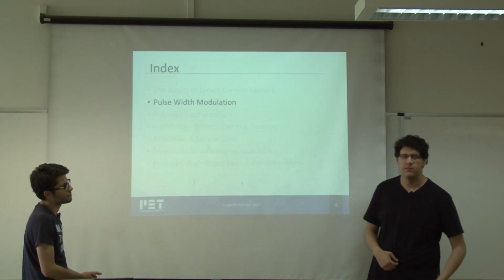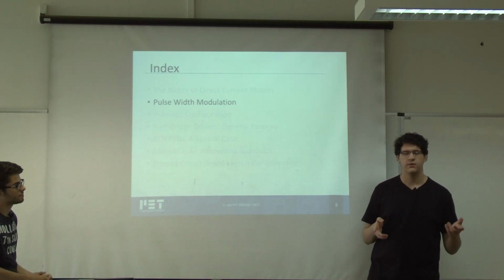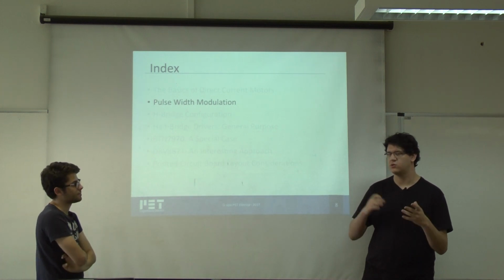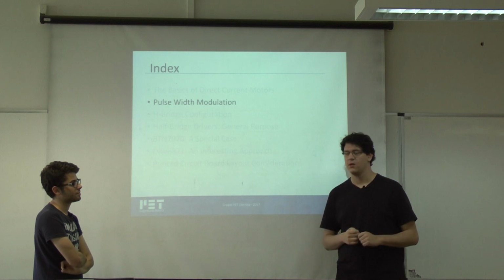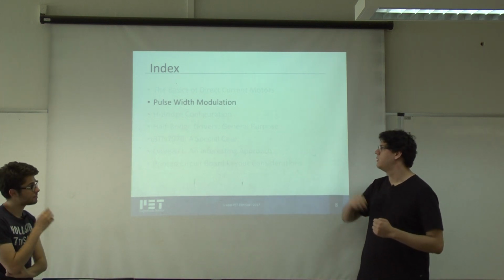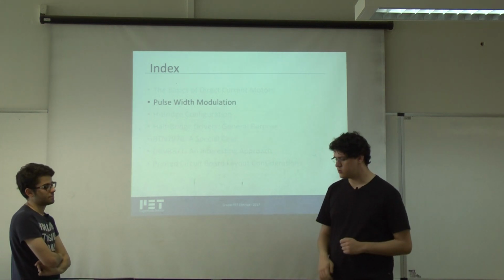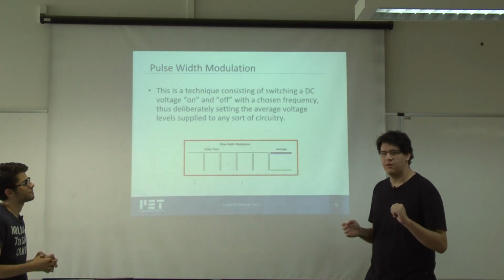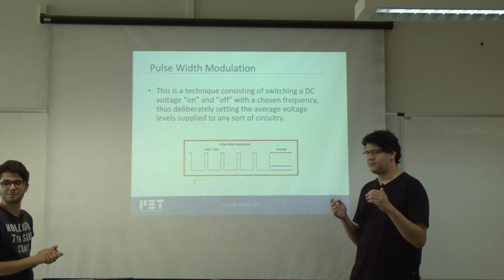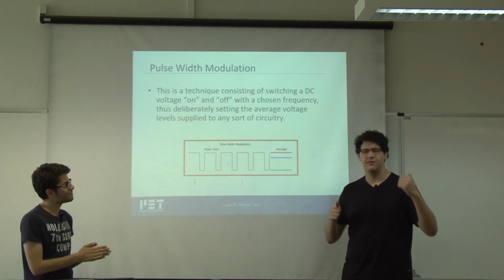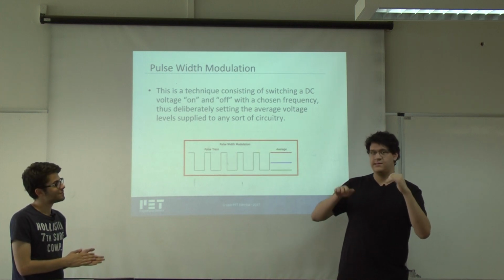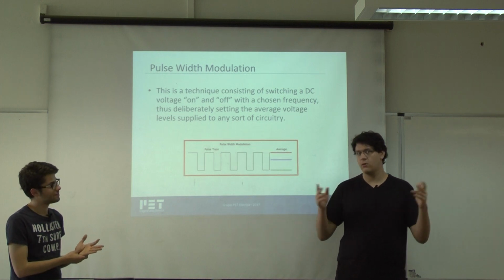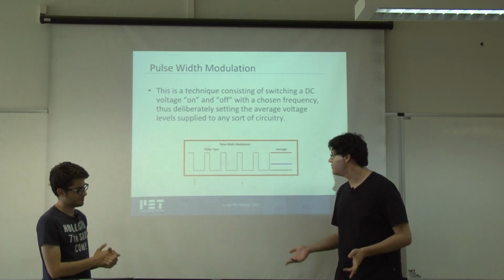And we were talking about how motors work, but we have to think about how to control the motor's velocity, the torque, or the acceleration. And we do this using PWM, the pulse-width modulation. So what is PWM, as we say it? PWM is a technique for modulating the DC level of a voltage across a motor or a load in the general sense. So this is how it works.